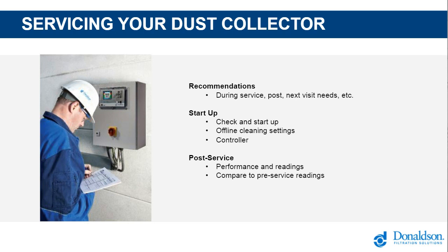And then moving on to post-service. Again, repeat those initial pre-service readings. Compare the performance between pre-service and post-service, and then draw any comparisons. And if anything's out of kilter there, then it may need some form of attention.